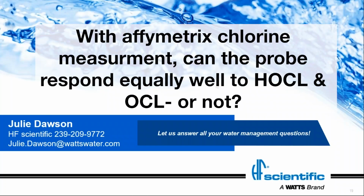No, it only reads hypochlorous acid. So it only reads the one species and then it looks at that dissociation curve to determine how much chlorine is in there. So it's not reading the OCl-, it's only reading the hypochlorous acid, not the hypochlorite ion. And then it uses the pH probe to determine what the chlorine actually is. So if you don't have a pH probe on there, it's really lost.